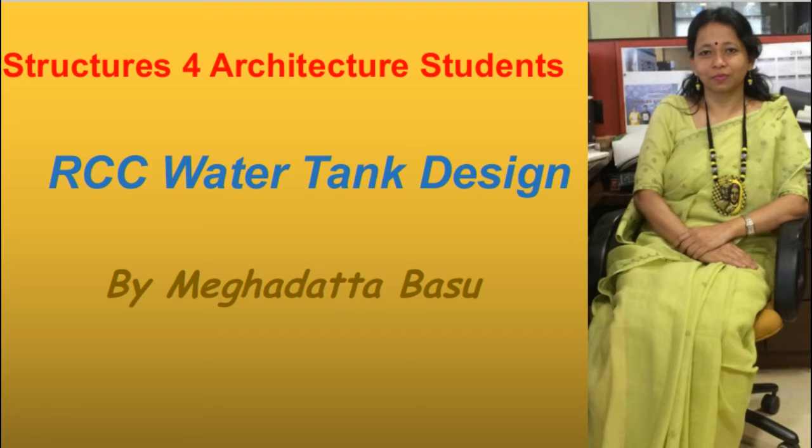Circular tanks with a horizontal or flat floor slab are economical for a smaller storage capacity of up to, say, 4 lakh liter, with diameter in the range of 8 to 12 meter. The depth of the storage is generally between 3 to 4 meters.